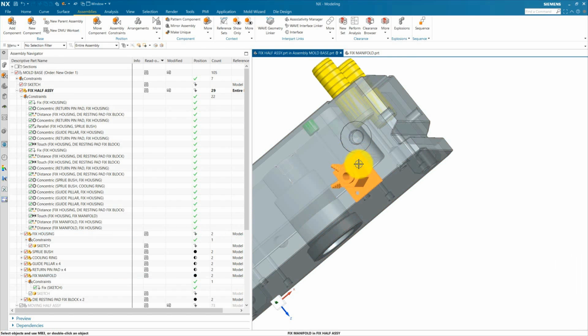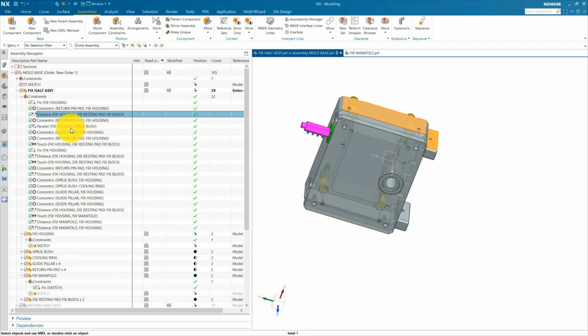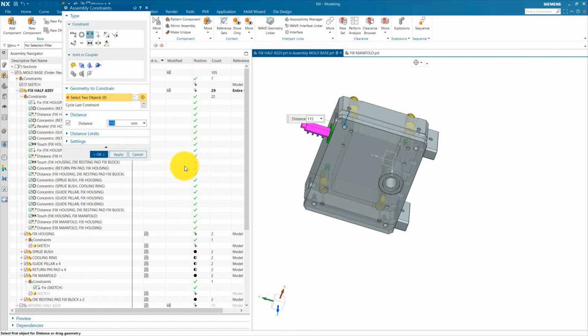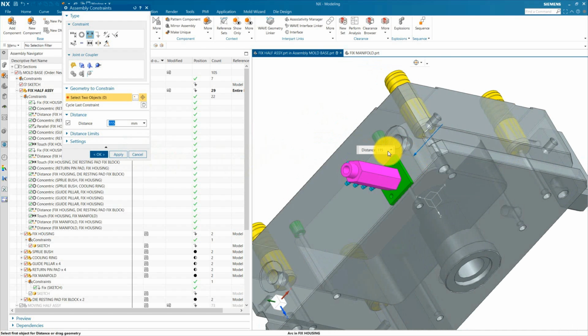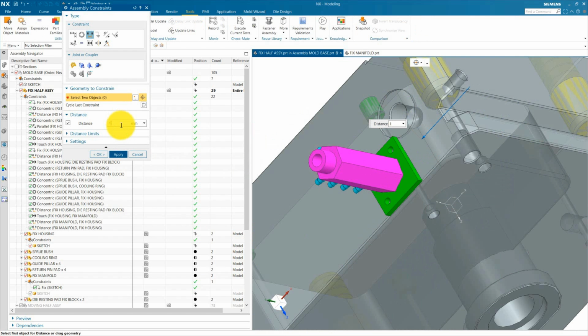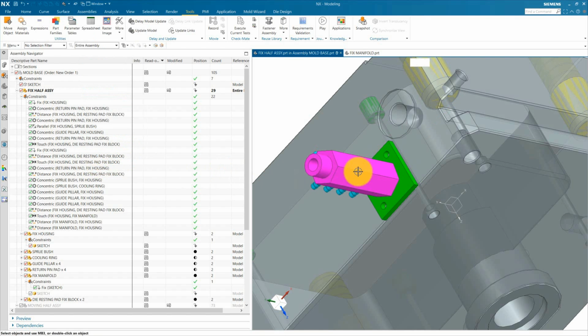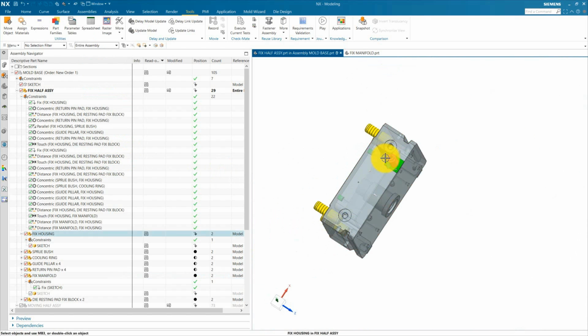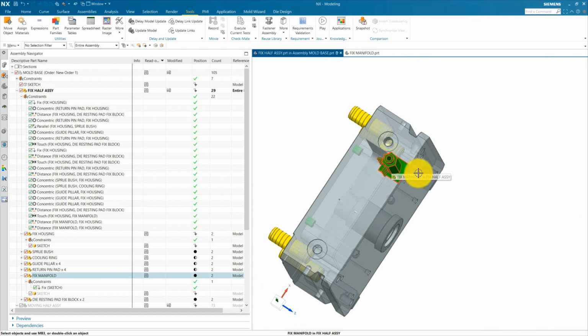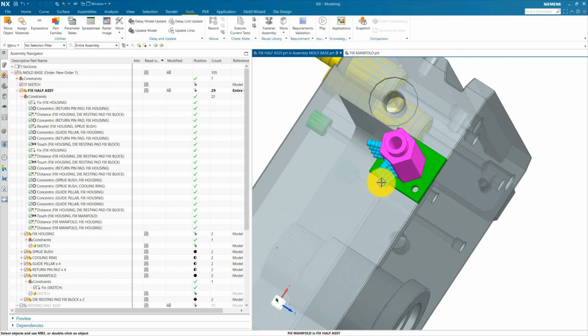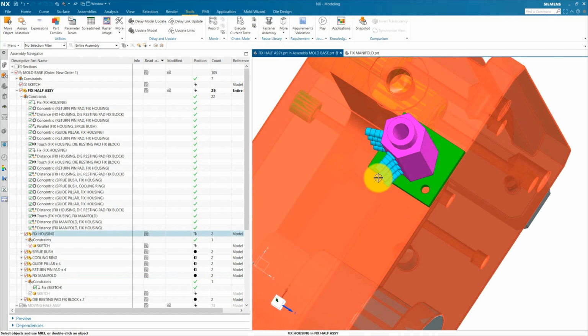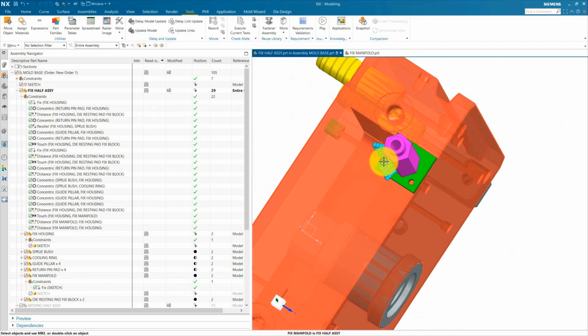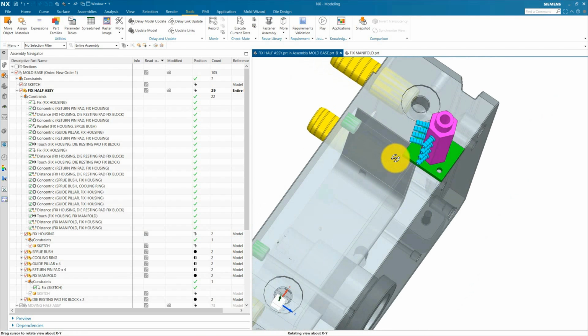So here we need to update the distance. For example, this is for the height pad, this is for the fixed housing and fixed manifold. We are going to increase the distance; for example, here we are going to use 130. Okay, 130 is okay. And make sure the rotation of the manifold is such that we can easily connect the pipe with our manifold nipple.